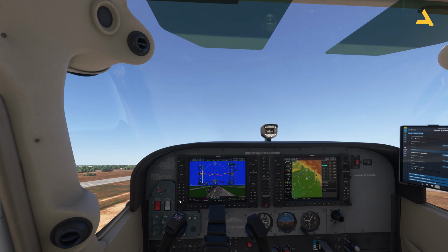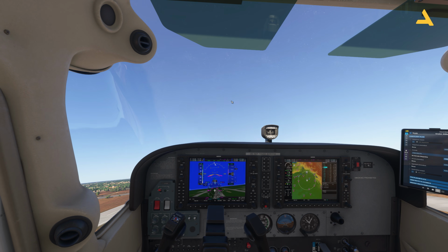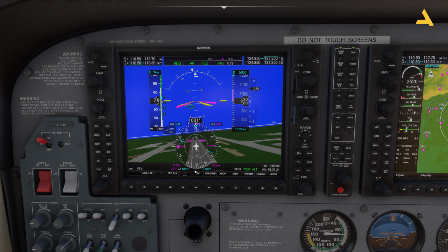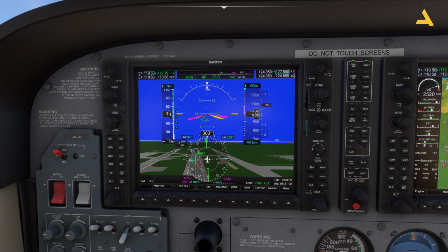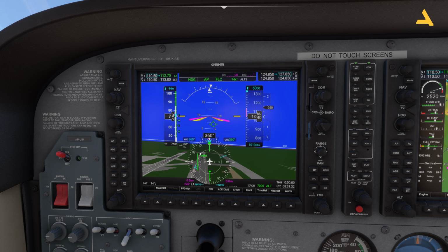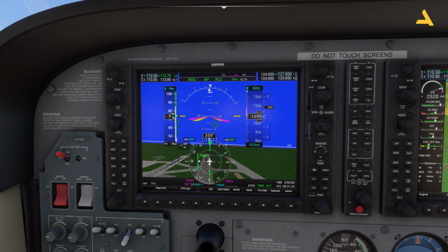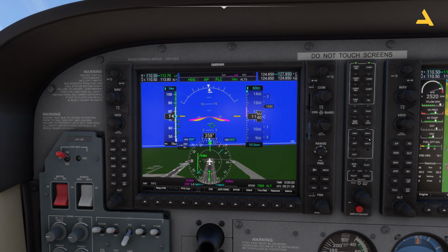And let me press flight level change for this. And that's it. Now let's look at the screen. Now I'm tracking this VOR. And you can see the course is on the left side. So instead of flying in this heading 360, I have to actually, let me just fix this course.